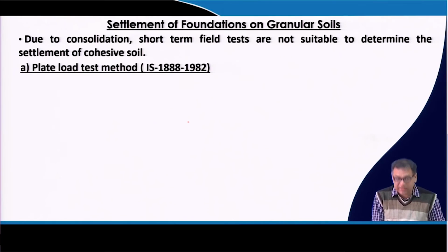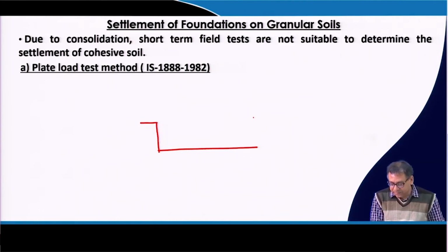It should be done at the base of the foundation. That means the depth of the plate should be equal to the depth of the foundation. Suppose we have a test pit, so this is the test pit.